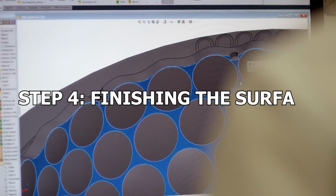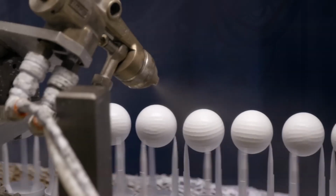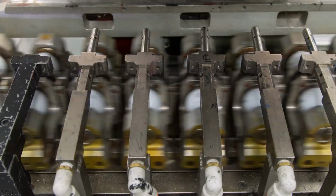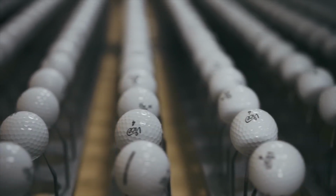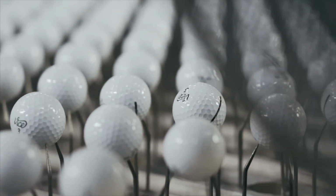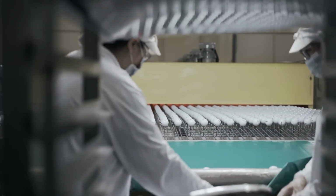Step 4. Finishing the surface. After molding, rough spots and seams on the cover are polished off. The balls receive 2 coats of paint, applied uniformly by spray guns, while the balls spin on posts. Next, logos are stamped onto the balls. Finally, a clear coat is applied to provide a high sheen and scuff resistance. Step 5. Preparation for market. Once painted, the balls are placed in containers and moved to large dryers. After drying, they are ready for packaging into boxes and other containers, prepared for distribution.